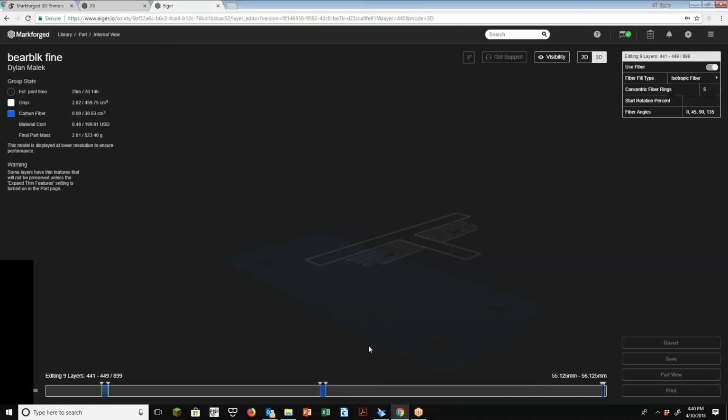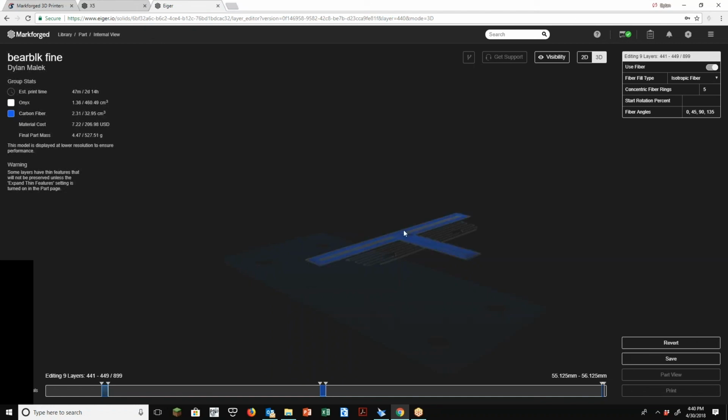So it'll do this little slicing on this area. And if my path width is thick enough, it will go through and actually add that in there. So it's doing it right now. There we go. Rotate it around so you can see a little better. All right, so it actually created all my concentric rings. I think I said 4, then it went in and created my isotropic path.